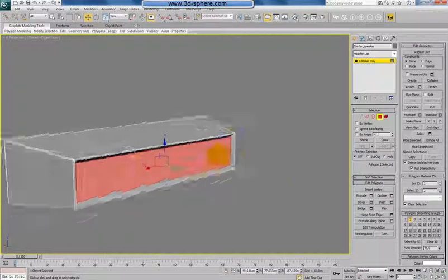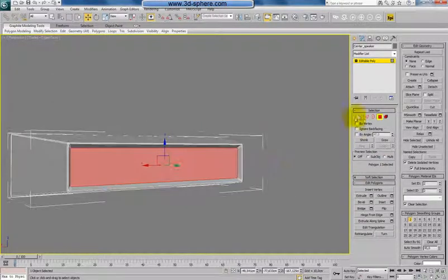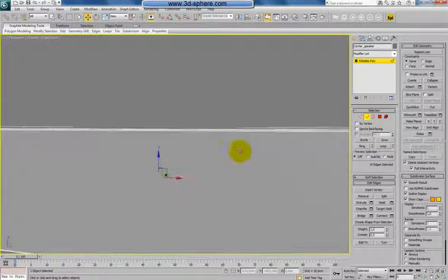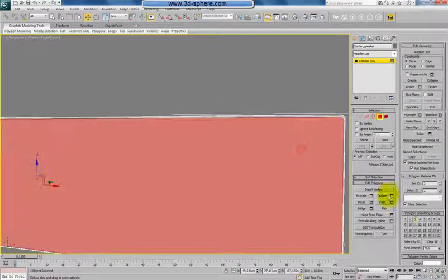Now here will be also the plugs like we did before. Now Control H on this shape and apply a chamfer. You can go with a bigger one, and of course also here we can apply an inset like this.